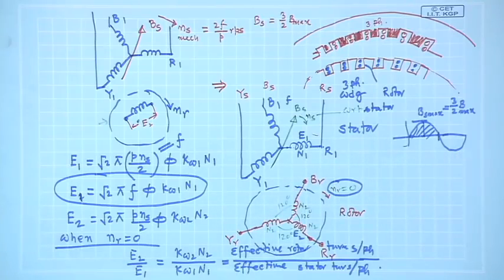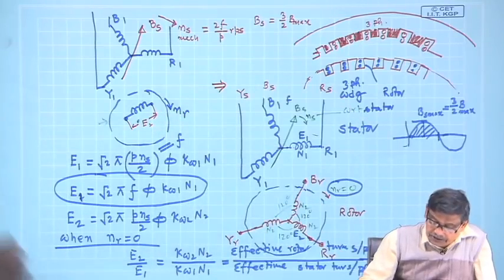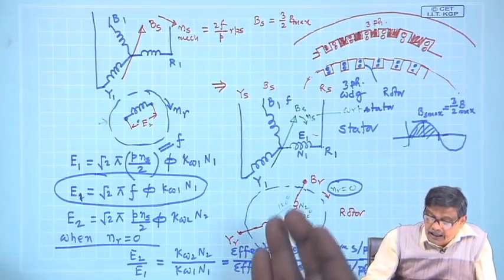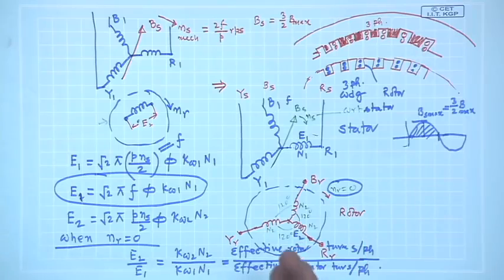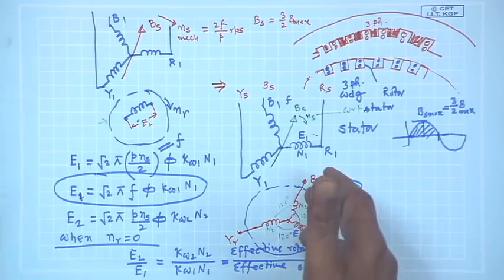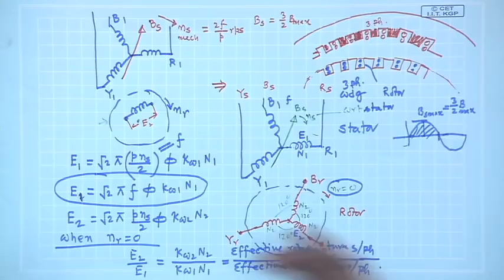F. So, it is almost like a transformer. Why almost? It is a transformer. It looks like you can step up or step down the voltages having the same frequency. But the only problem is I do not know yet what is going to happen if the secondary winding also starts carrying current, whether it will remain the same in its operation like a transformer or it may differ.